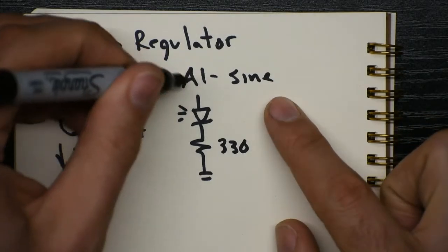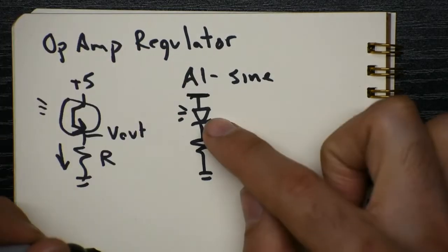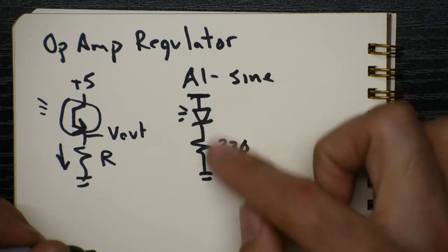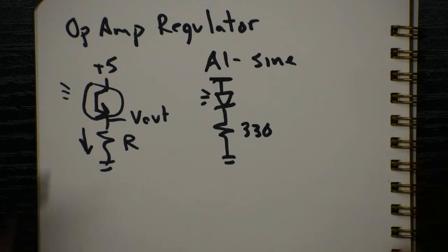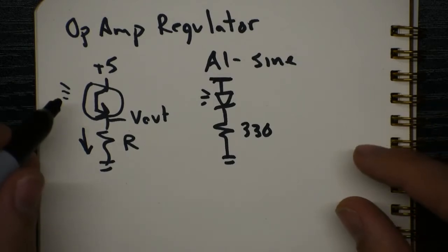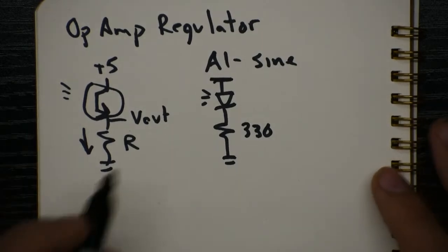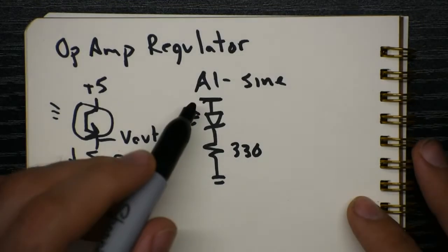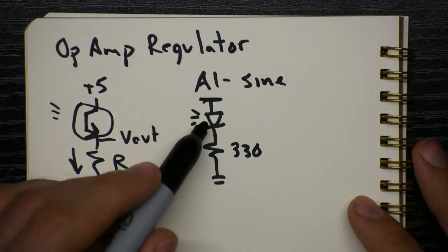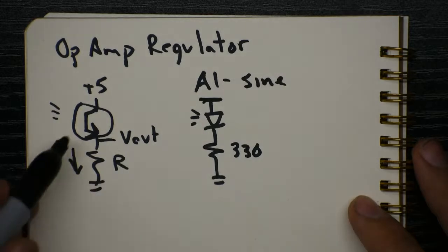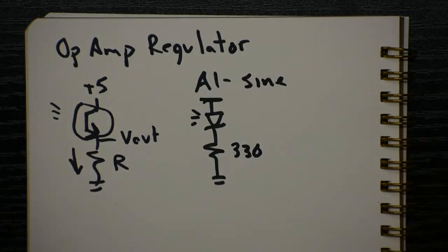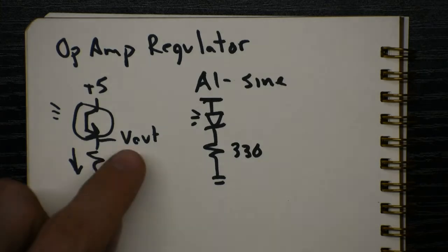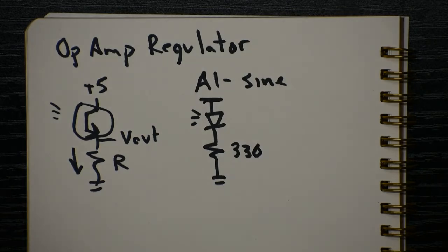But instead of having A1 attached to the LED, we're going to use the op amp. Now, that ends up being a relatively simple circuit, so I'm not going to draw it for you. You'll have to find that as you go through the lab. But let's build this first part of the circuit. So we will have the sine wave go into the LED. Light will come out. It'll hit the phototransistor, and let's look at what that output voltage is, and then think about how we can use our op amp to make the output voltage become a sine wave.